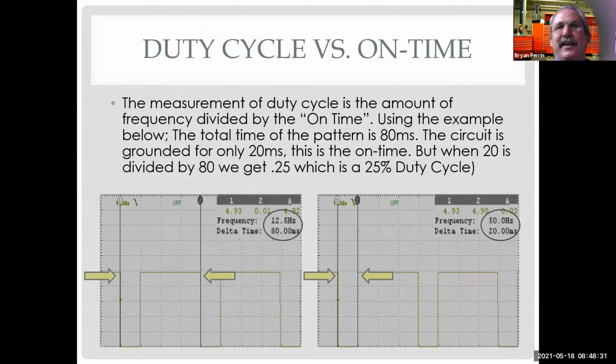So you see that by using the duty cycle, instead of having a dial to dial the voltage up and down, we're giving it full voltage, but for only short periods of time. So it's effective voltage. And if I put a meter on it, because meters are so slow, I would literally see 3 volts, 6 volts, 9 volts as I change the duty cycle.